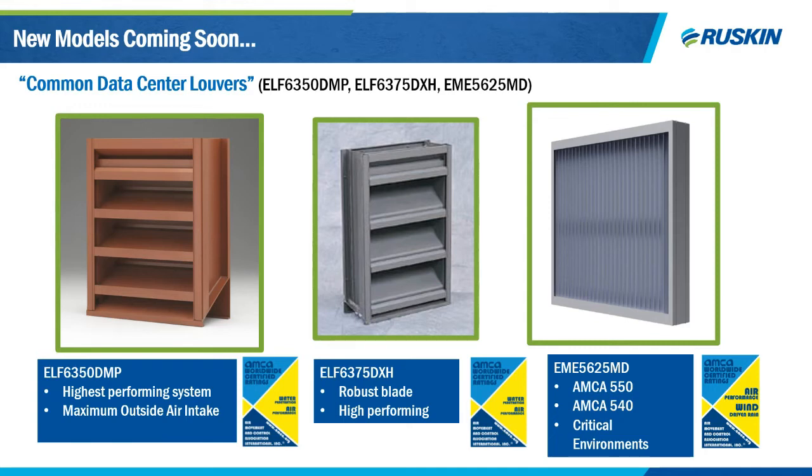Next up, the ELF 6375 DXH. This is slightly more robust while still maintaining that same high performance. It has a 1/8 inch thick frame and blade construction. And this model also offers excellent water penetration with 57% free area, also making it highly specifiable. So this also has more than 50% net free area.